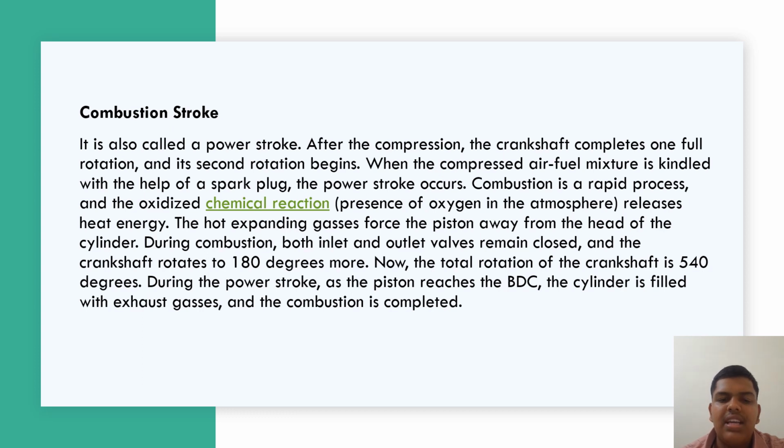The hot expanding gases force the piston away from the head of the cylinder. Both inlet and outlet valves remain closed and the crankshaft rotates 180 degrees more. Now the total rotation of the crankshaft is 540 degrees. As the piston reaches the BDC, the cylinder is filled with exhaust gases and the combustion is completed.